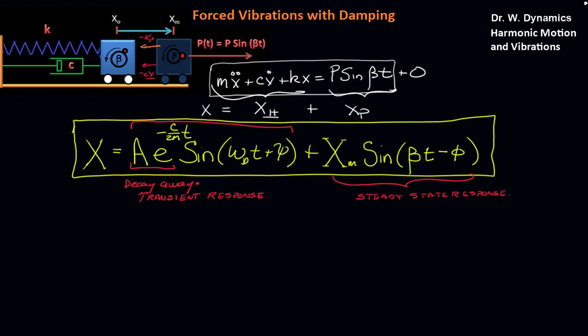When we're looking at a damped forced vibration system, when it's initially turned on, both responses are active, and the motion can be fairly complex as it builds up speed. However, over time this one disappears, and generally in the long run we're worried about this term right here, and that's the one that we usually focus on.